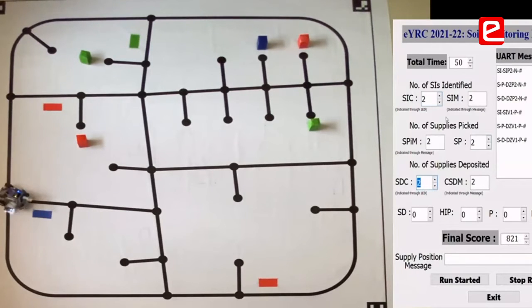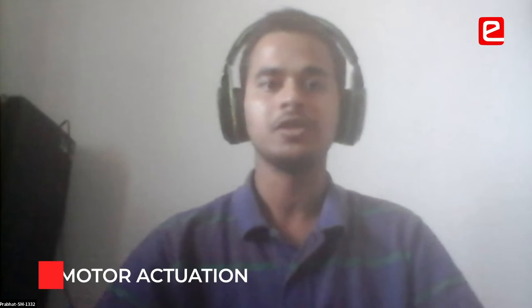Why is it necessary to complete it in one clock cycle? No, sir, it wasn't necessary. It's just that, as we know, the for loop will only exit once it completes, so the FPGA had to somehow manage to compute everything in that one clock cycle previously. But now we are using multiple clock cycles to compute it. As it is, we are running at 50 megahertz, so it's quite fast compared to the motor actuation. Motors have their own inertia, so it will take a millisecond for them to react, and here everything would be done in microseconds, even after, say, 100 clock cycles of the 50 megahertz loop.